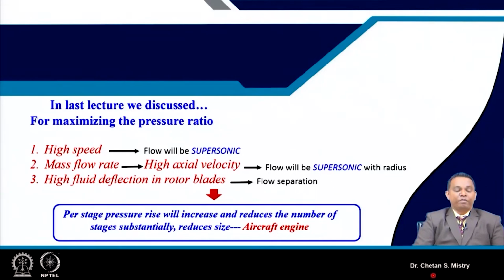The third option we have discussed is having higher fluid deflection for the rotors, and that will lead to the flow separation issue. So discussing the first two options, my flow is going to be supersonic, and that is of major concern or interest for these lectures.